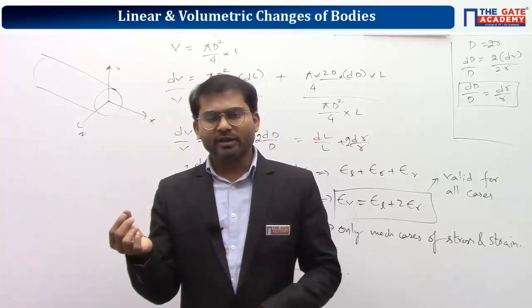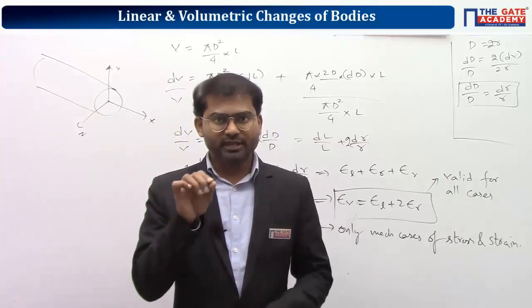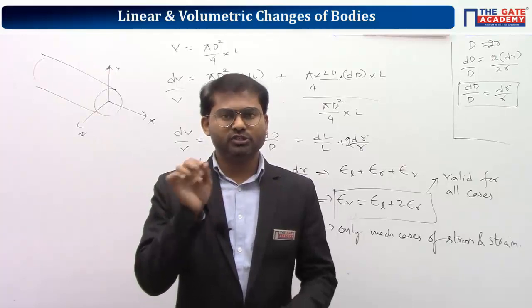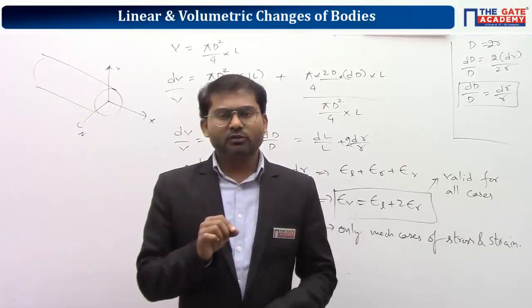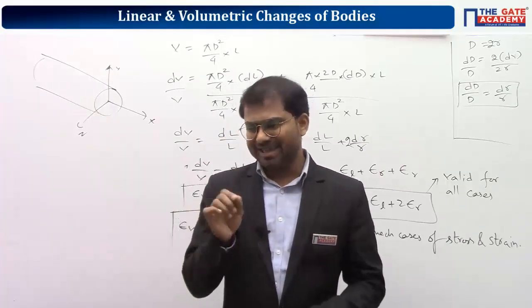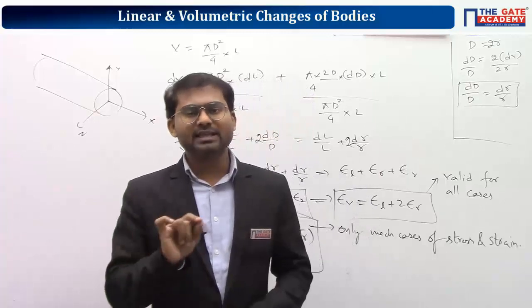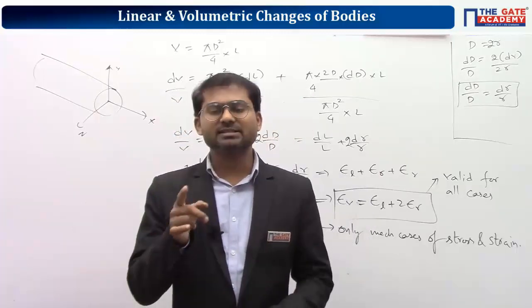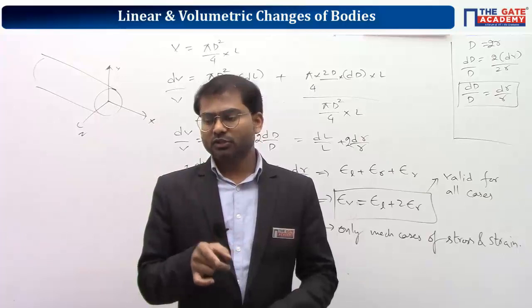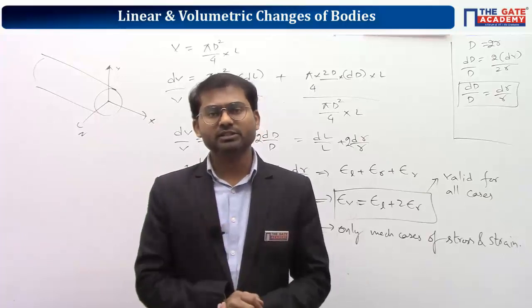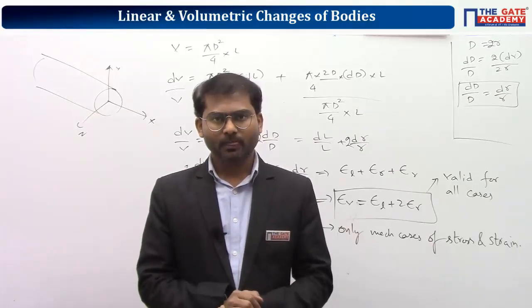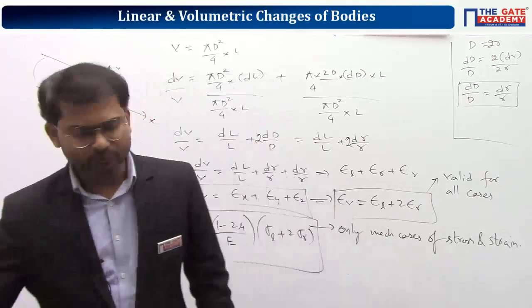Let's substitute Poisson ratio as 0.5. You should get the value to be equal to 0, right? So if you substitute Poisson ratio as 0.5 in option number A, C and D, you will not get the answer as 0, except in option number B. So the correct answer for this question is B. Like this you can get the answer very fast. Okay, otherwise you can simply substitute as well.